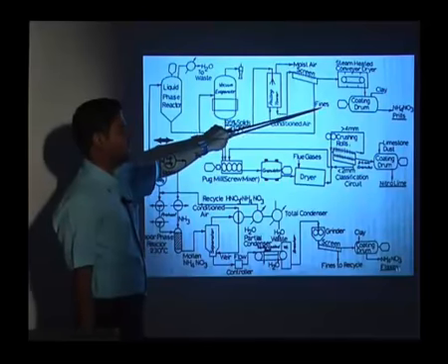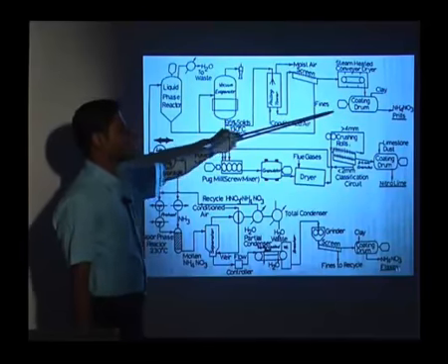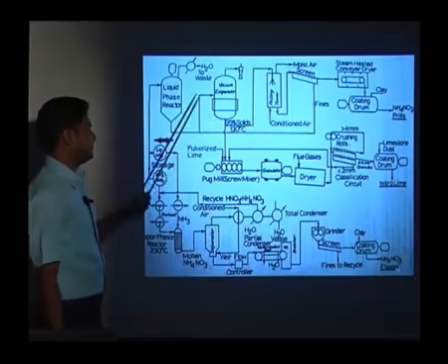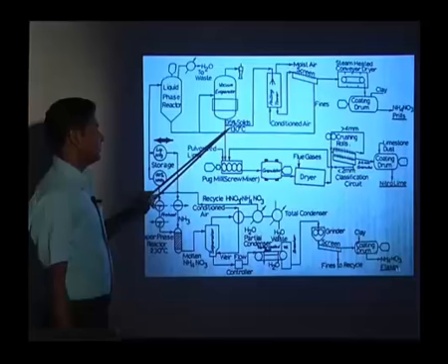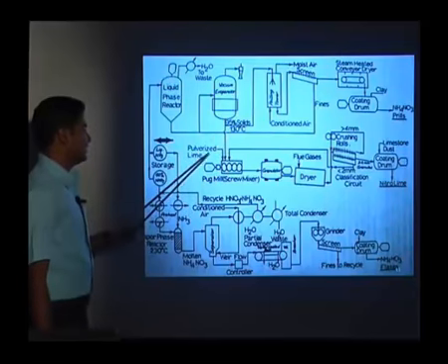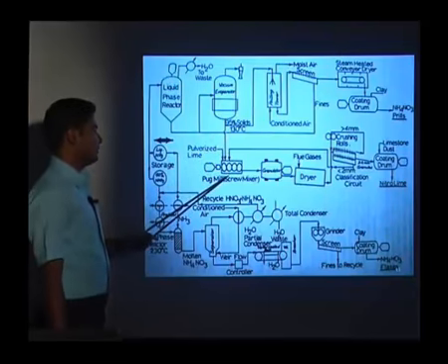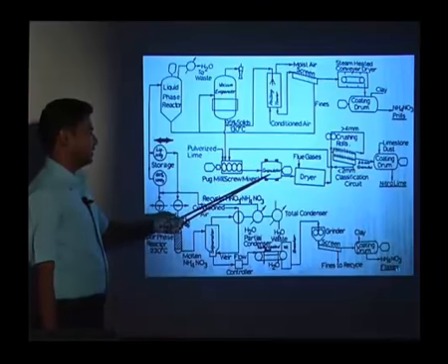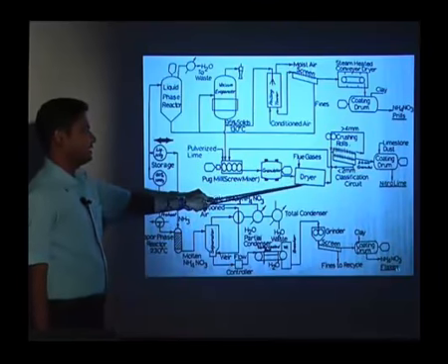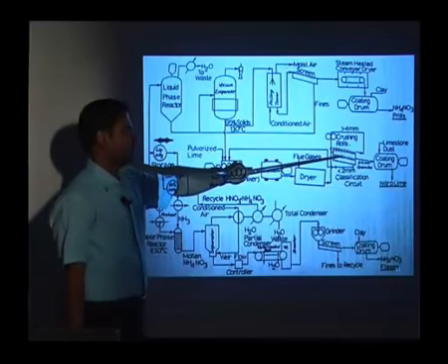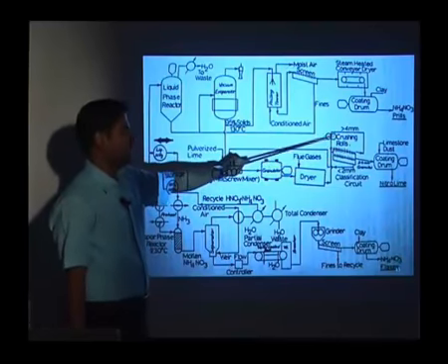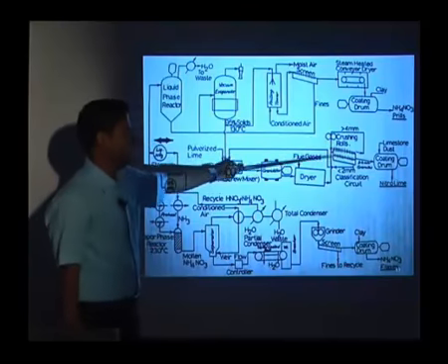The fines are recycled back and we get the NH4NO3 prills. Or the ammonium nitrate, 95% solid at 130 degrees Celsius, we can mix with the help of pulverized lime. Then we can send it to the granulator where it granulates, then it is dried, and then it is sent to the crushing rolls. Suppose the size is more than 4 mm, then it is recycled back,